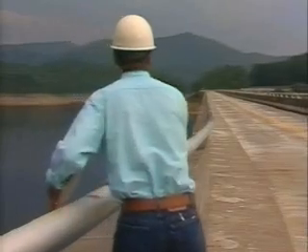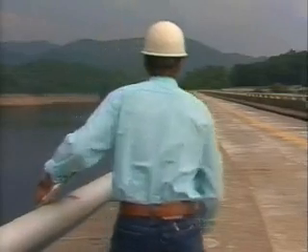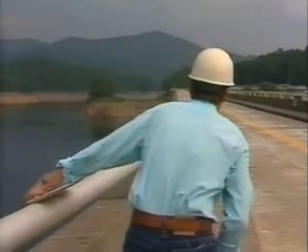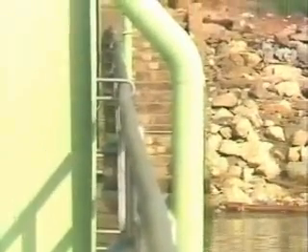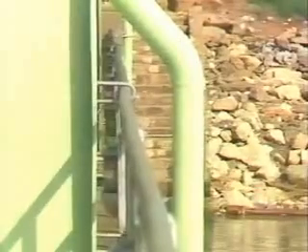First, sight along the crest directly above the linear feature. Next, move or lean to one side and sight along the feature. Then lean to the other side and again sight along the feature. Crane rails and handrails are two examples of other linear features that could be used to detect displacement along the crest.